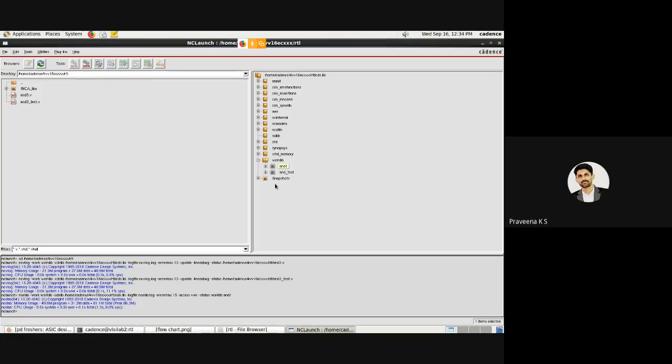So elaborating is basically it'll try to read the code. So it's a Verilog code. Then it will try to recognize its corresponding hardware modules, right? Whatever hardware modules you have written inside the code, it will try to recognize those modules. That will be put into synthesis format, and all the netlist errors, and that will be for constraints, design constraints. So they're going to check, and it will elaborate, and it will recognize its RTL structures.